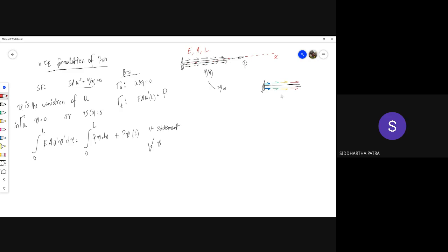Okay, so that is also a possibility, but in this case, even if we had uniformly distributed load, by double integration you are going to get a quadratic function. So even if we think of u being a polynomial in x, that would at least be a quadratic polynomial for a non-zero q. Just keep that in mind. That is the exact solution, or in order to get an exact solution, you need u of x to be at least a quadratic function, even if your distributed load is uniform.